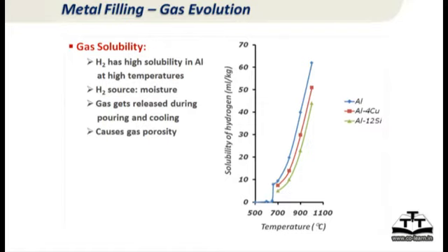How much gas are we really talking about? If you look at aluminum alloys, which absorb the largest amount of hydrogen gas, where does hydrogen come from? Moisture in the air and moisture in, let us say, the mold. Look at the values here. At the melting temperature, the top blue one, the amount of gas absorbed is almost 60 milliliters per kg.